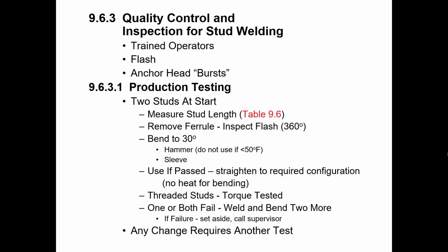And then it's just a matter of, did the process of bending that stud over break the stud off or fail the weld in some way? If it didn't, then you're good. You can bend the stud back or leave it. Sometimes the engineer will say you can just leave it bent over. That's okay as long as they've approved it. You don't have to heat it for bending it back up.